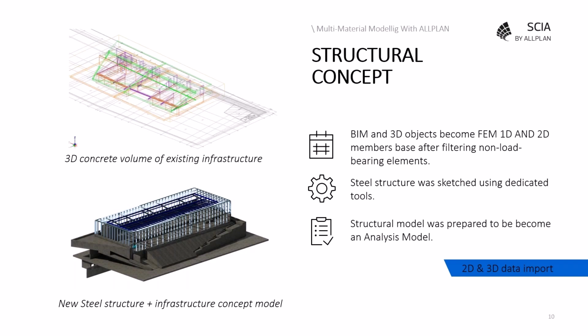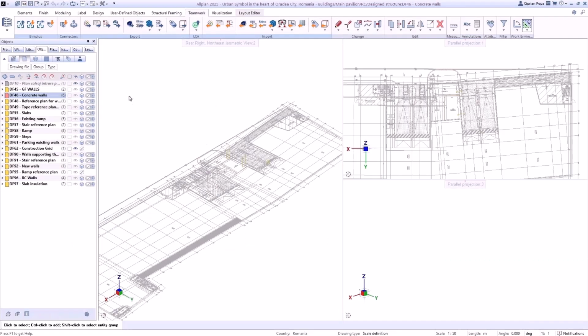And the tool for this is Allplan. So in Allplan, basically we remodel some of the items. Although we have everything looking good, behind the scenes we might not have BIM objects. So we might not have native IFC data, which contains attributes such as material, numbering, role, and so on. So that kind of data is relevant to be modeled in a BIM authoring tool such as Allplan. So let's see exactly how this works.